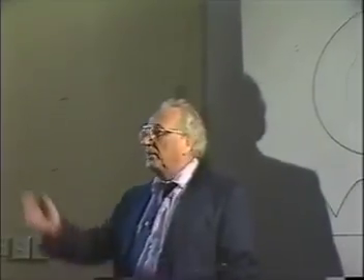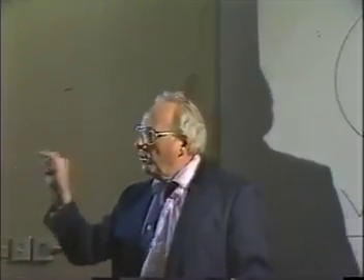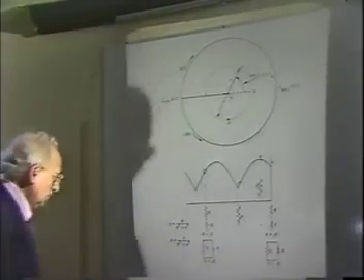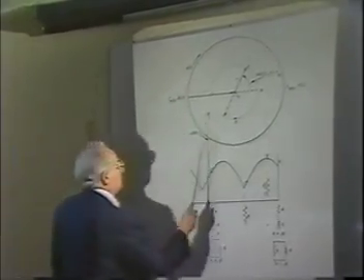Now you see the basic idea of matching. The places you can match a transmission line are only on that Z0 circle. That's the only place you can match it. So when you're doing this physically with the circuit elements, that's the only way it could be done. Let's go back then. Look at this one more time easily and slowly, because you cannot forget this.